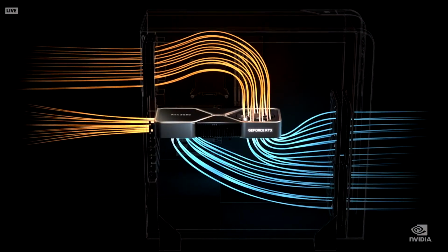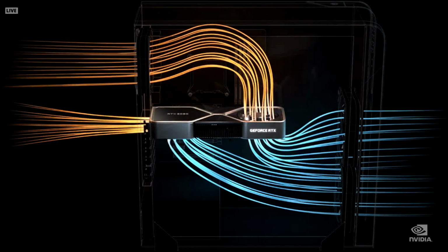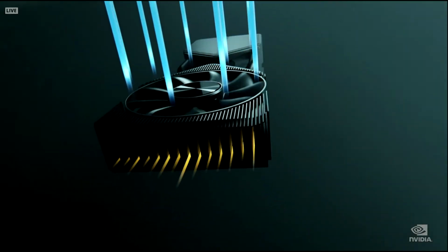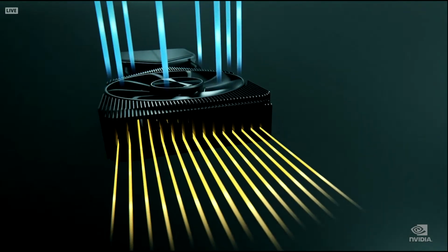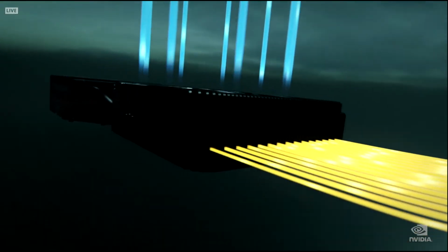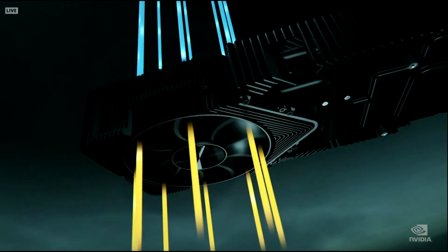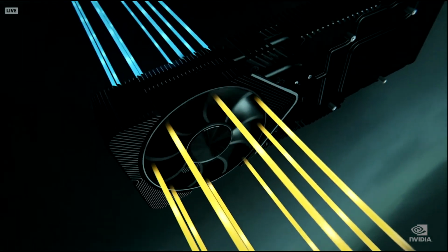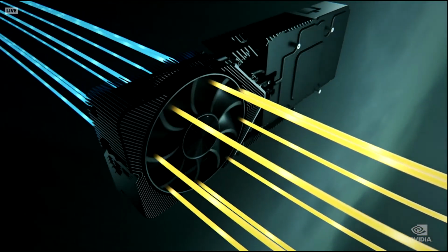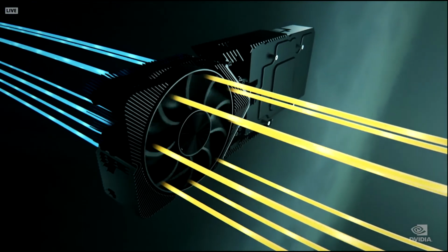There are 2 independently controlled fans. The bracket front fan pulls cool air from the bottom and pushes the heated air out through the graphics card brackets. A backside pull-through fan passes cool air over the fins of the heat pipe and directs the hot air to the top and back of the chassis to be exhausted by the system fan. The 3080 flow-through system is 3 times quieter and keeps the GPU 20 degrees cooler than the Turing design. It can cool 90 watts more than Turing.